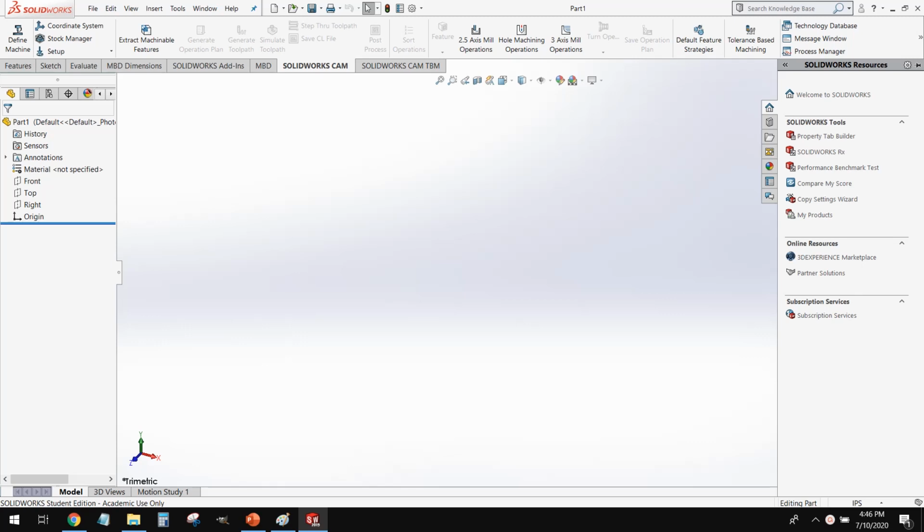So in our last video, we talked about threading and fasteners. So now we know what quarter 20 UNC means, right? So what we're going to do is show how we apply this in SolidWorks. And there are two methods to apply threading. There is physically modeling the threading, and then there is what we call cosmetic threading. Cosmetic threading essentially paints a veneer of threads onto your part. So it looks like threading, but there's no actual teeth modeled. And we'll talk about the pros and cons to each, but we're going to run through both of them today.